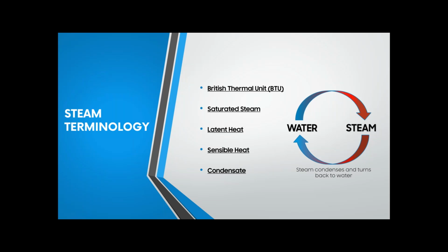You also may hear the term wet steam sometimes. Wet steam is just a mixture of steam and water. It's not considered suitable for proper efficiency of heat transfer. You'll use wet steam sometimes in a steam gun to clean the pavement or clean some equipment covered with oil or dirt. Remember, for every temperature of saturated steam, there's a corresponding pressure. We'll see that when we get to the steam chart.